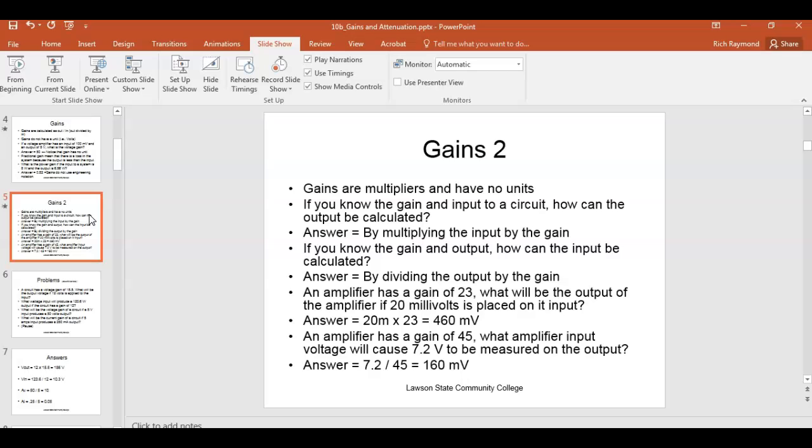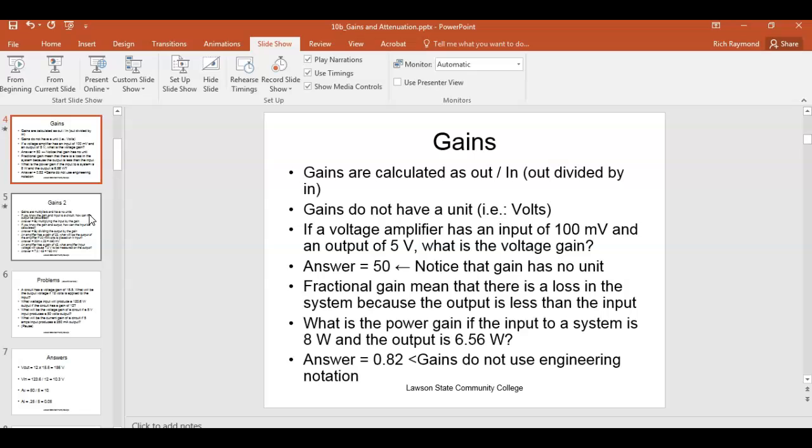I think I told you about my mom and her stove. Did I tell you the story? My mom gave me a call and says, Ricky, she called me Rick, my stove won't even boil water anymore. And I went out there, and instead of getting 240 volts to her heating element, she was only getting 120 volts. So instead of getting 1,800 watts, she was getting 1,800 watts divided by 4. And it wasn't getting hot enough to even boil water. I went out, she has a breaker box outside, and I realized that she didn't have 240 coming from the line. One of her leads had burned off her transformer. So I don't know if it got something across it or something like that. So instead of getting the 240, she was only getting what? 120.